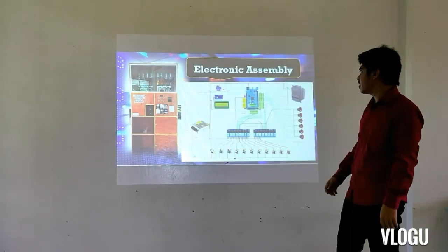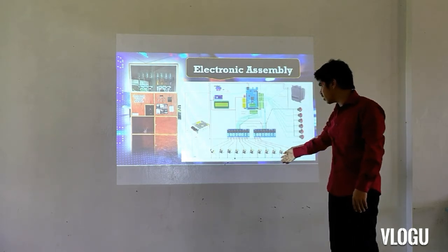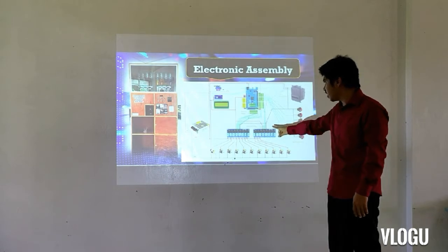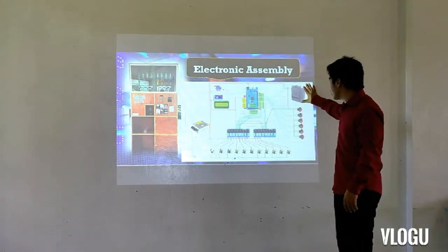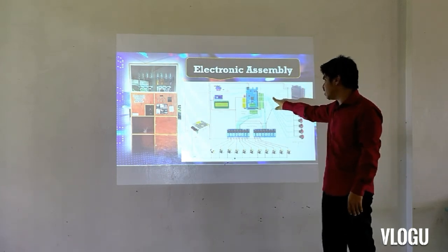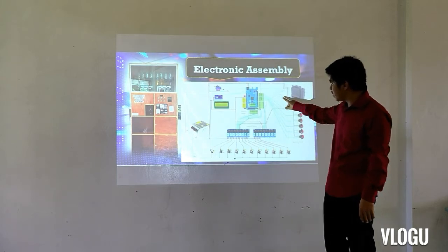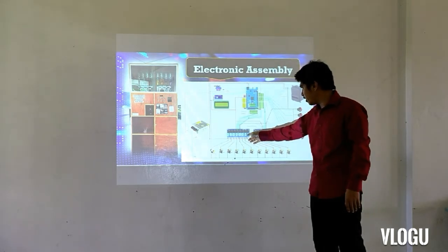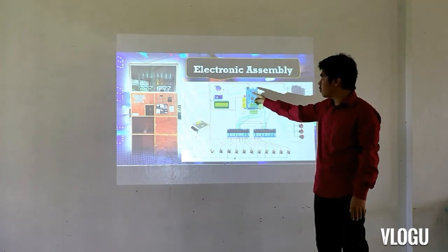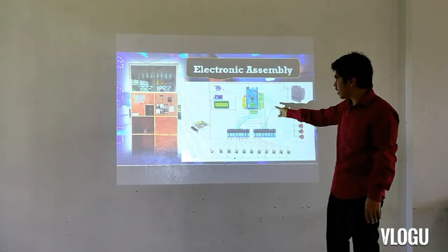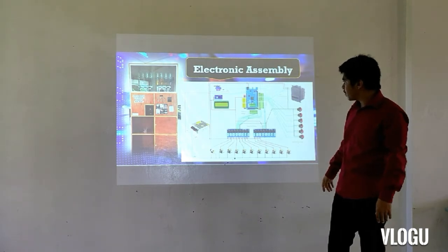In the electronic assembly, we have here the Arduino Mega, which is connected to the 12 volts power supply together with the bill acceptor and the motors. The other main components like the switches, the relays, the LCD screen, and the servo are on 5 volts. In the connection of the bill acceptor, the output signal is connected to digital pin number 2 of the Arduino Mega, and the switches are on digital pins 3, 4, 5, 6, 7, 8 of the Arduino Mega. The relays are on digital pins 22 to 32 of the Arduino Mega, the servo motor on pin number 9, and the LCD screen on the SCL and SDA pins of the Arduino Mega. And that's all.